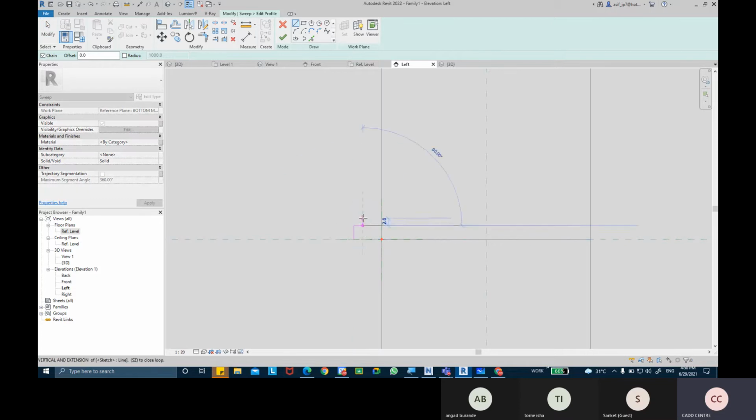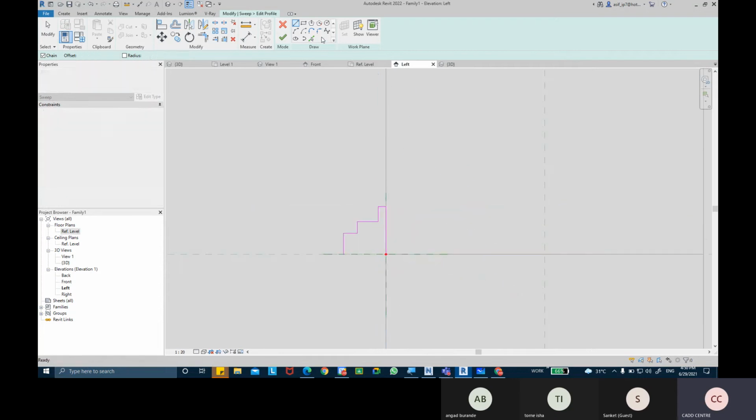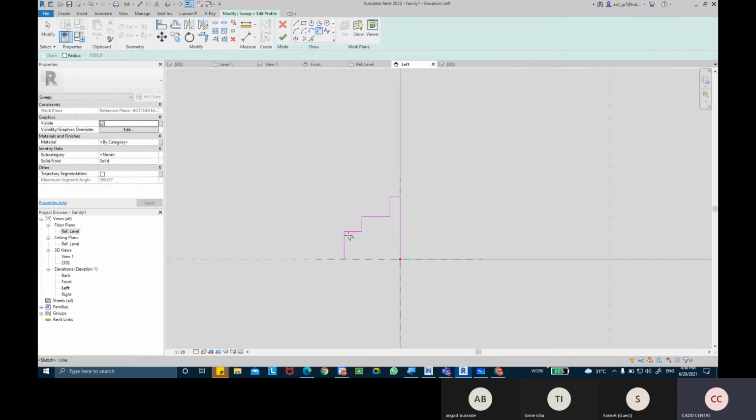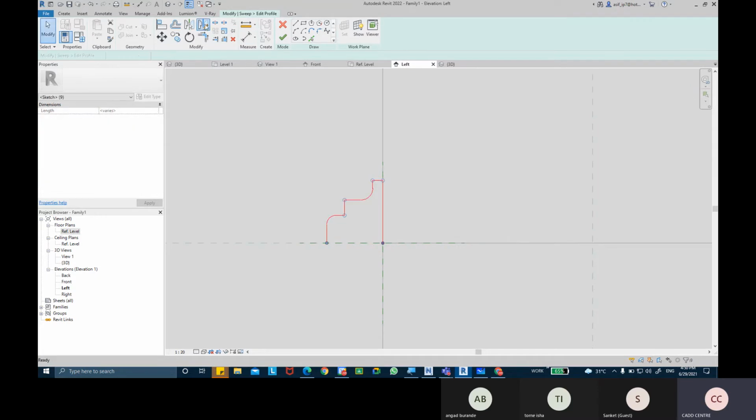So I'm going to once again take a very rough sketch of that profile design, and like that you can fillet them if you want to give these curves a little bit of arcs. And I'm going to mirror it on the other end as well, so mirror tool, bottom end.